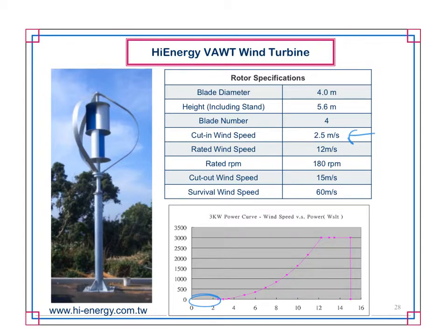So essentially when your system is being turned on, you are starting to generate electricity and interconnecting to the grid. If your speed is below a cut-in speed for a long enough period of time, the electronics and the controls are still going to be energized, but your generator is not going to be energized. You're going to let the system freely spin so that you're not putting a lot of load on the system, as long as it doesn't overspin, and it shouldn't, because the wind is so low. You're really going to try to minimize, because at that point, you're actually taking power from the grid, and you have to pay for that electricity.